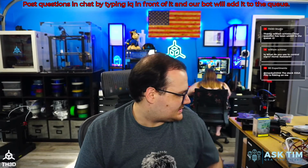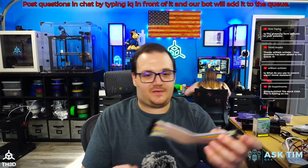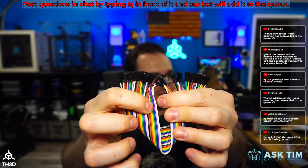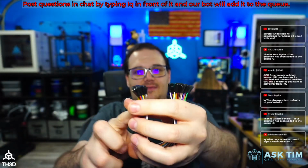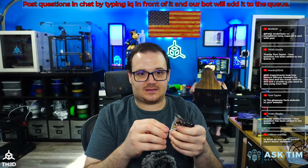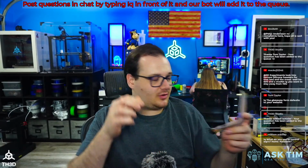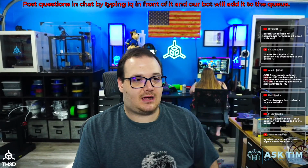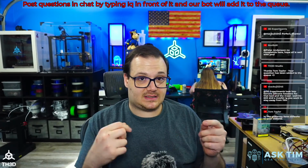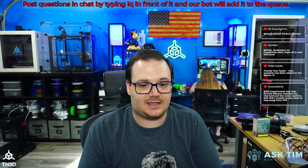But you could always use my favorite little things, which I use in this project. These are female to female, but there are other versions of these jumper wires, and we actually sell these in our shop, that have a male connector with a pin sticking out. So you could literally figure out what the pins are on the board, jump it over to the plug on the LCD, and make your own little adapter harness. I've done that with testing. It's actually how we figured out how to wire and design the PCBs for the adapter boards: moving them around, making sure everything works, documenting it, and then making a PCB.